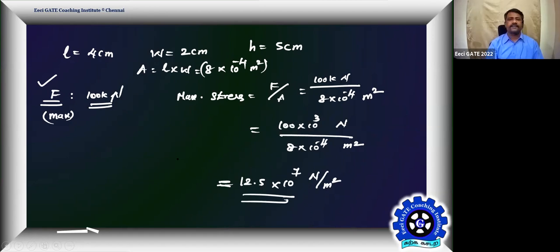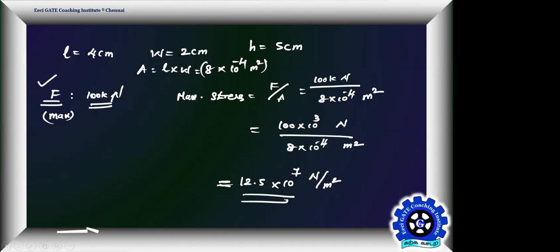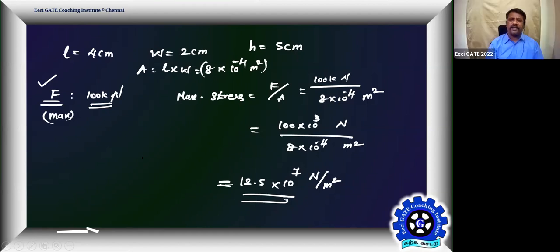Correct? Following, right? Yes, sir. Now tell me, what is the strain in the metal block? That is your load cell. What is EL, the longitudinal strain? I'll also get an estimate of ET as well. EL is nothing but the longitudinal strain, which is force per area, that's your stress, divided by Young's modulus of elasticity. For that we need this data.